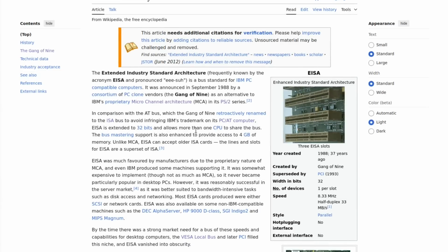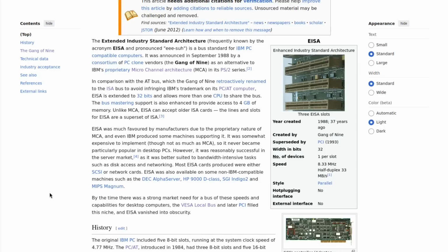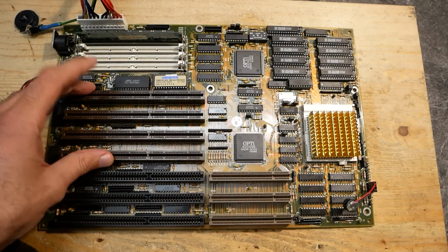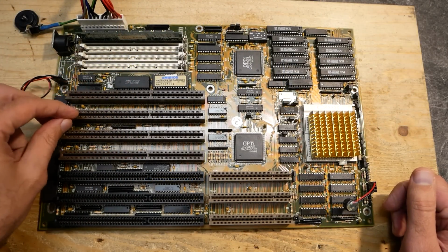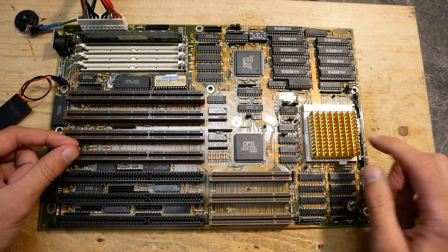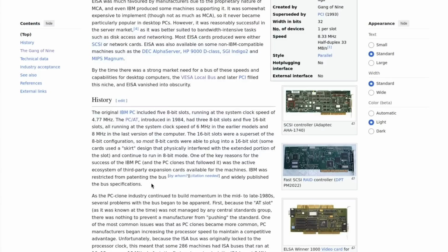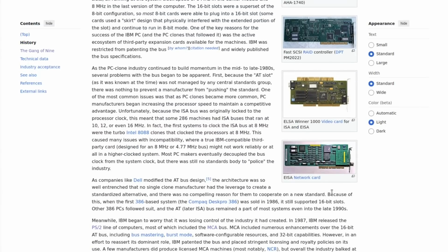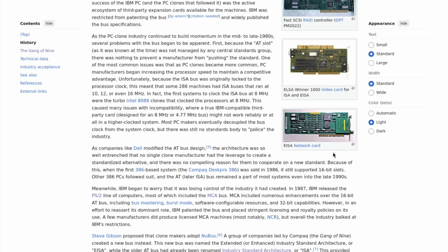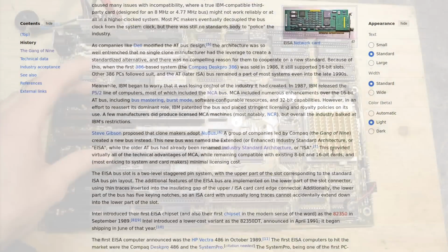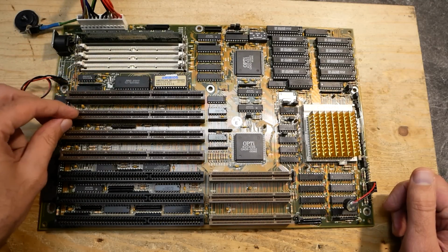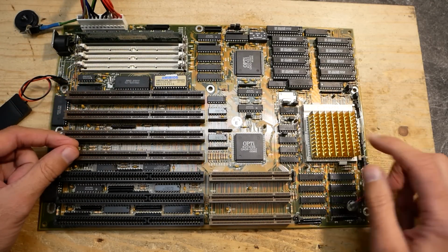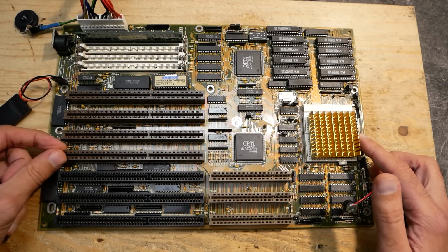It had nearly the same list of supported features as MCA. It supported up to 32-bit wide data transfer, bus mastering and configuration per software, which shall be the actual topic today. EISA was primarily developed for servers and workstations, so most expansion cards for it were network adapters, SCSI controllers and similar stuff. So basically hardware which handles a lot of I/O and would benefit from better bus control flow. EISA hardware was obviously more expensive than ISA, and so it was rarely used in private computers and office machines.